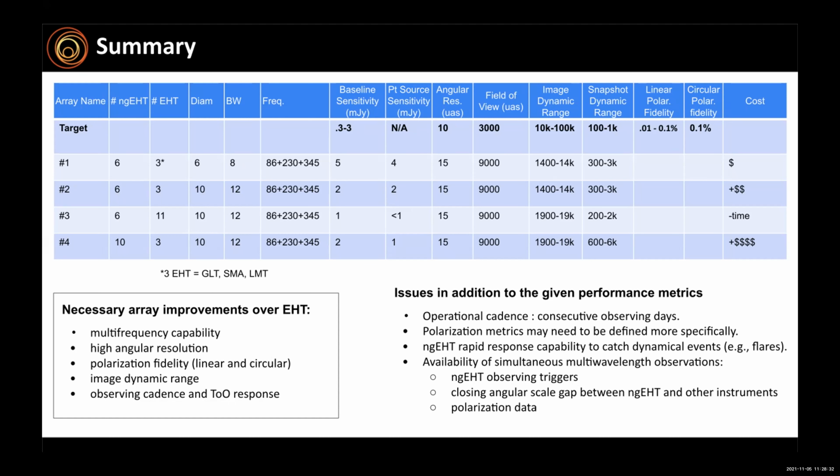and above. I think the general sentiment was that's very expensive. And then you run into problems of antenna design being incompatible with the lower frequencies. So it's very difficult to have an antenna optimized for both 86 and 600 at the same time. So that's an engineering challenge.